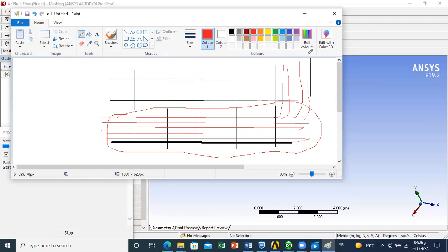Okay, and in this way, you will be able to divide your zones into smaller parts without causing any discontinuity in these regions. Now when we see the mesh together, I will do a cut for you so that you can see how inflation is done. For example, for the cylinder, inflation will be done like this. Because you already did inflation on the floor, it will continue from the floor towards the cylinder.